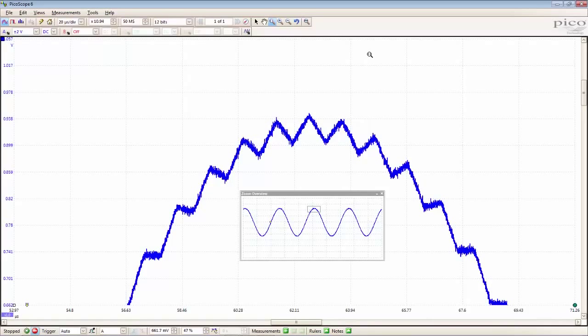We can see that it is a triangular waveform that is noise that's sitting on top of that sine wave. So that gives us the information that we need to go and search for the source of the noise that is causing the problems to the acquired waveform that we saw in the first place. We're now seeing it with good clarity, enough to make measurements and draw conclusions which will help us to find the root cause of the problem.